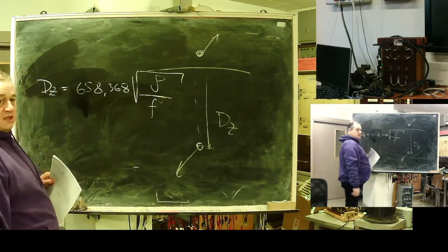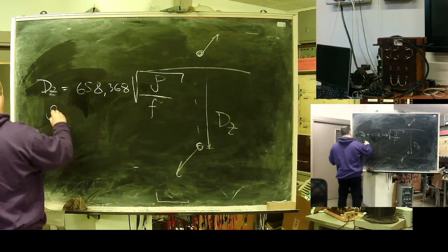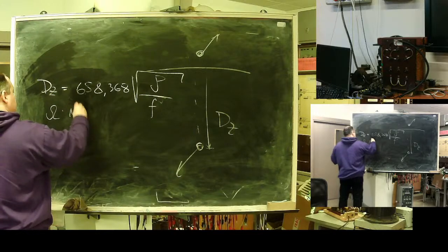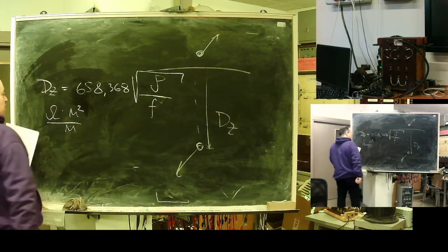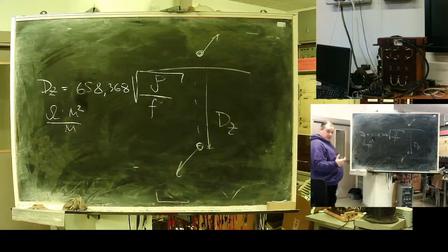Rho is the Earth resistivity, measurable in ohm-meters. So if you take, let's say, a plastic pipe with a cross section of 1 square meter, fill it with this ground, and the length is 1 meter, you will get the resistance.